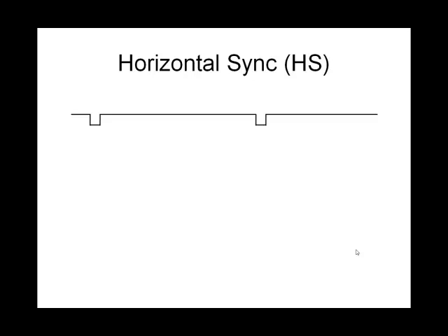For the purpose of this discussion, the first phase we'll discuss is called the display phase. And this is the largest amount of time within the period. During the display phase, we have values being displayed on the screen in raster order from left to right. The color values on the 3 analog signals will be drawn in time during this display period. For this particular resolution that we're going to use in this lab, 640 by 480, there will be 640 pixels worth of time that are displayed in this display region.